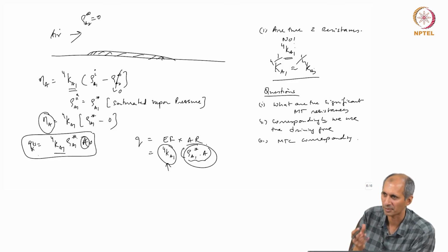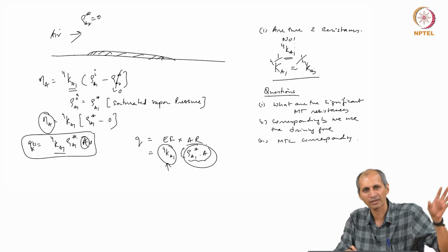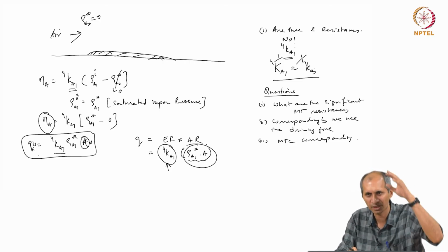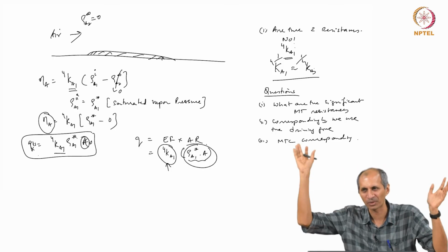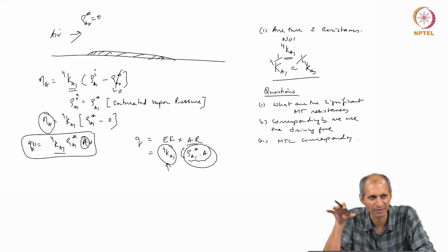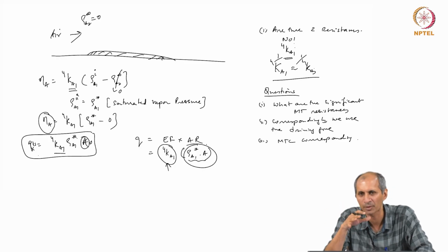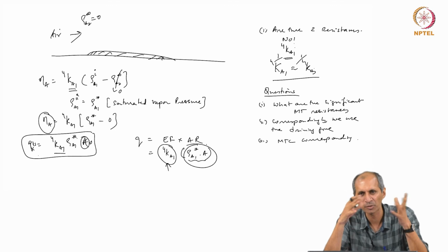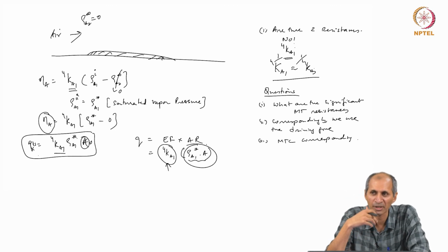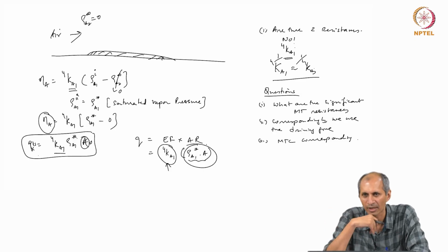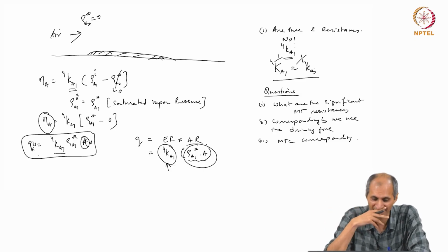The Q is the highest possible number, that is one. Second is, if you are talking about exposure, the wind speed and stability class are the most stable. Unstable, you do not have to worry, it will disperse fast, but the stable, that is the worst case scenario. If you do not know anything about wind speed, you say, okay, I assume it is stable, and then calculate. It is over solving, it is over designing, but from an environmental point of view, it is always a safe thing to do. It is better to be safe than have a big disaster, that is a problem.